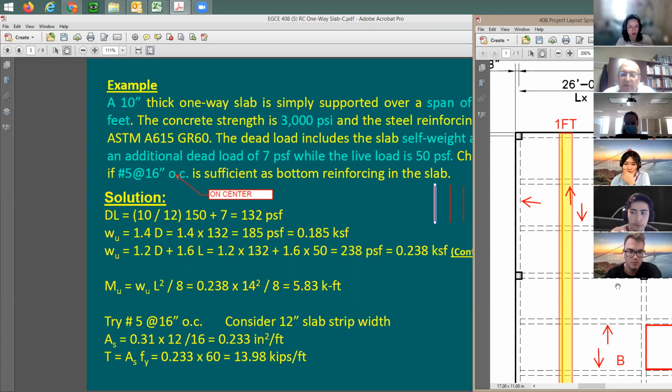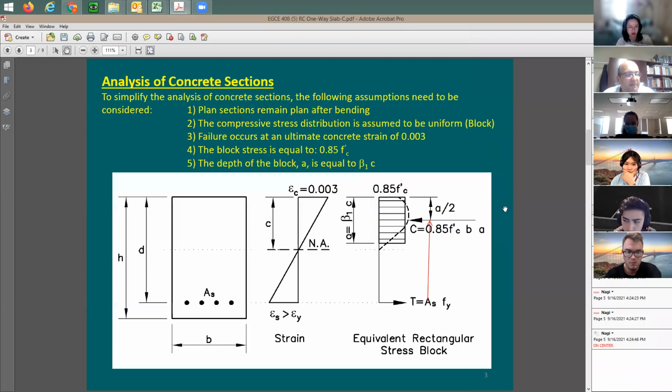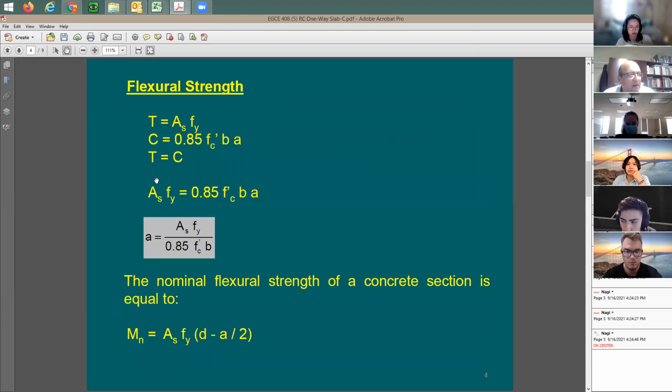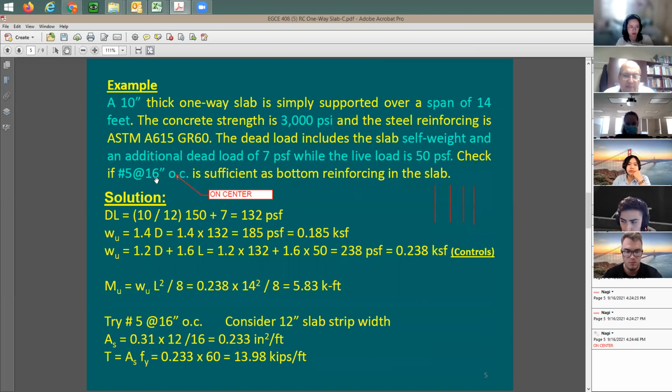So it's a big issue. How would you figure out the amount of reinforcement that you added in this width? In concrete beams, for the given width, we're going to mention how many rebars you put here. So you can say, for example, 2 number 9 plus 1 number 8, or 2 number 8 plus 1 number 9, or maybe 3 number 8. We can just mention the amount of rebars here. In our case, when we have a concrete slab, we're going to be considering the width to be only 12 inches. I'm not going to be taking it to be 16. As a challenge, how would you figure out the amount of reinforcing that you put in this strip of 12 inches wide?